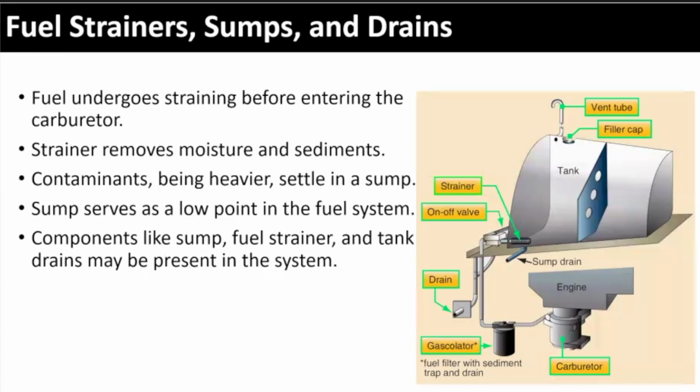If you happen to see water or sediment when you drain that tank, you take a sample, throw it away in an environmentally friendly way. Take another sample. If there's still water or sediment, take another sample. Okay, you get to the point where it's clean, you're good. If you get to the point where you say, I'm not flying this airplane because I can't get rid of the water and the sediment, good idea to scratch it for that day, call the mechanic. Get them to look at it and drain the tanks and get them cleaned out.